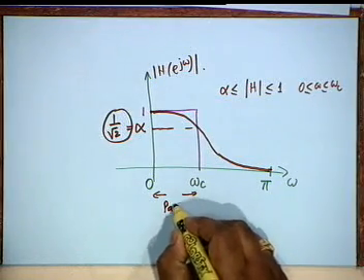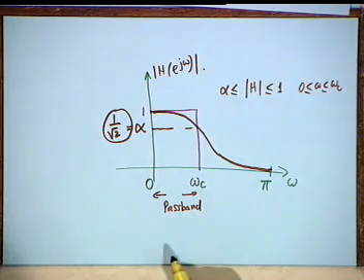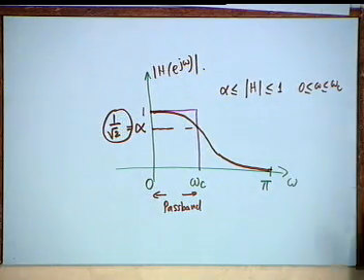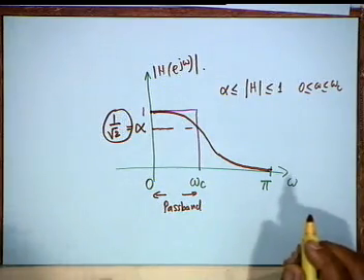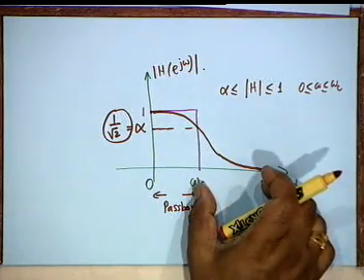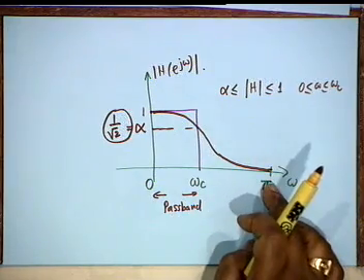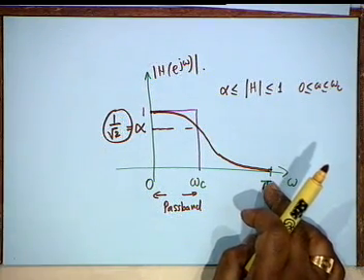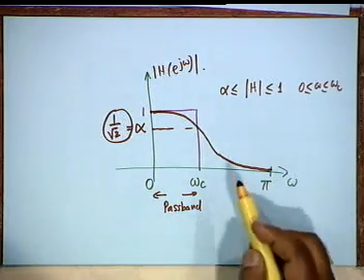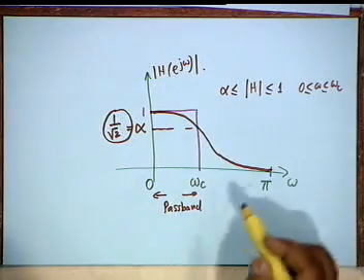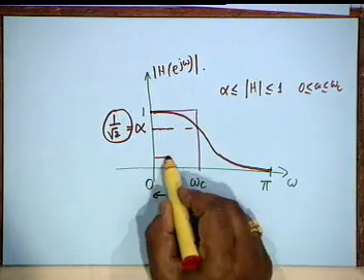Okay. So, this range is called the pass band, and then you have to define a stop band. Ideally the pass band is 0 to omega c and the stop band is omega c to pi. However, from omega c to pi we cannot have 0 response for this extended range. What we could have is 0 response at some isolated points if we allowed ripples, but in a monotonic response we have to define another constant beta